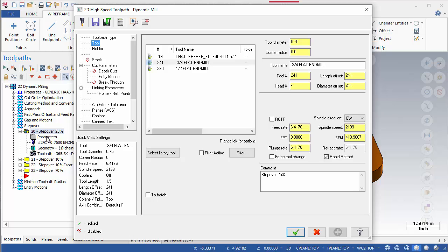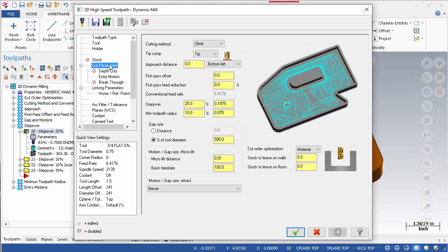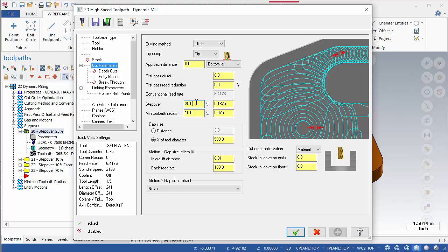The Stepover setting is located in the middle of the page. Stepover sets the distance between cutting passes in the X and Y axis. Here you can specify the Stepover as either a percentage of the tool's diameter or key in an actual distance. Make note that when using Bullnose type cutters, the percentage is based on the flat bottom portion of the tool.